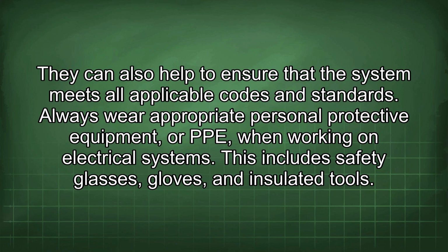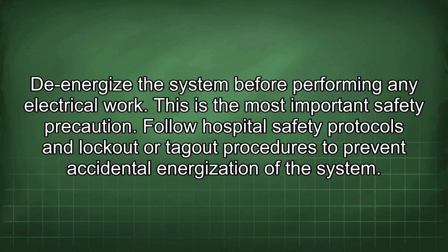Always wear appropriate personal protective equipment, or PPE, when working on electrical systems. This includes safety glasses, gloves, and insulated tools. De-energize the system before performing any electrical work. This is the most important safety precaution.